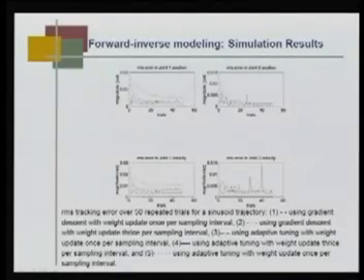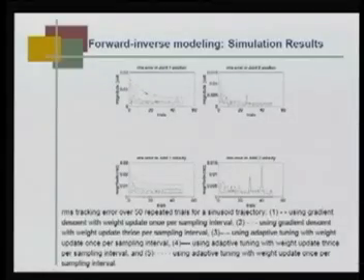Now, with this initial random weight, we used various algorithms. First is gradient descent. So, what we did is that we simply updated the weight according to the gradient descent, and you see over 50 trials, the error in joint 1 position is, this is trial 1, this is the RMS error, and slowly the RMS error reduced and it is here. But when we use the gradient descent, but with weight update thrice per sampling interval, then you see that error further decreased.